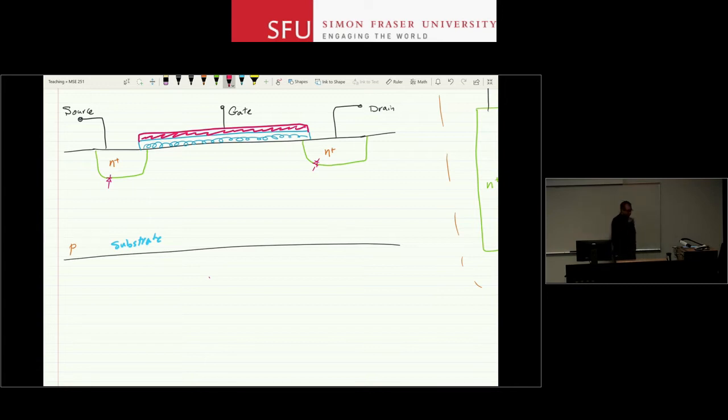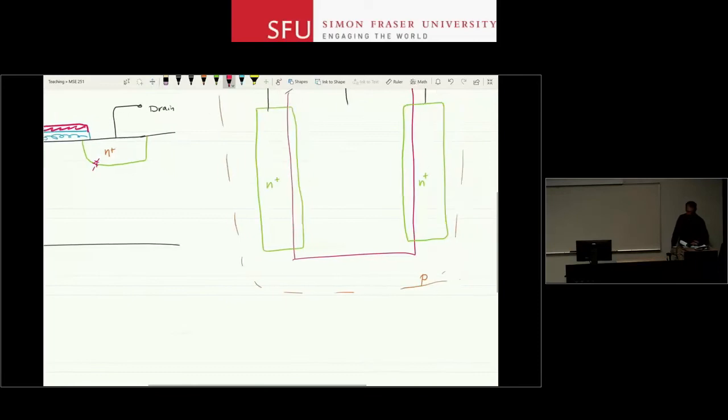And again, if you go back and check your physics, you immediately realize that this is a capacitor. This combination, a conductor at the top, a dielectric here, and a conductor at the bottom, that's a capacitor. This is how we actually make capacitors on chip, on wafers. So I make a capacitor like that, but what is special about this capacitor is that I have put two highly doped regions at the two ends of this capacitor. The top view will look like this, right?